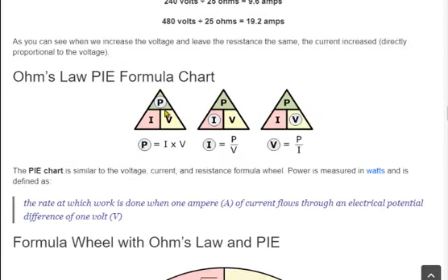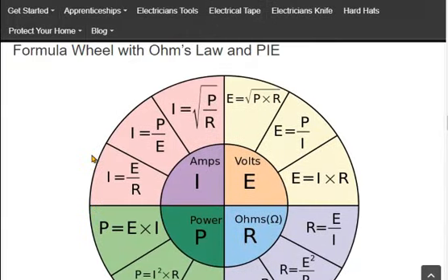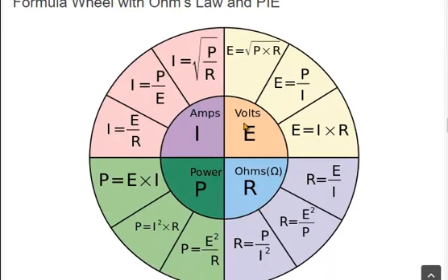And then they get to the power law. Here's similar for the power law in the original one. And then they put it all together, and whoa, you have this big power wheel. There should be a capital V all the way through here, that would be pretty cool. You recognize certain forms of these depending on what you're solving for. But then again, I have nothing of this memorized except just two forms. Right here, power equals voltage times current, and the other one is resistance equals voltage divided by current, and everything else derives from that with one or two algebra steps.